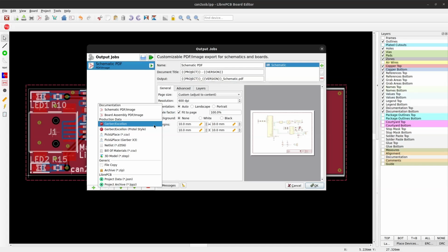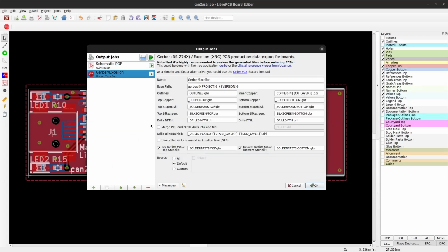Since naming of Gerber files is not standardized, you need to check our manufacturer's documentation to choose the correct settings. Our first preset uses settings which we consider as most reasonable. But especially cheap PCB manufacturers are often not able to handle them correctly, thus the second preset is optimized for those cheap manufacturers. However, we cannot give any guarantee that they work correctly with any manufacturer. Please also check out our documentation about all the available configuration options.